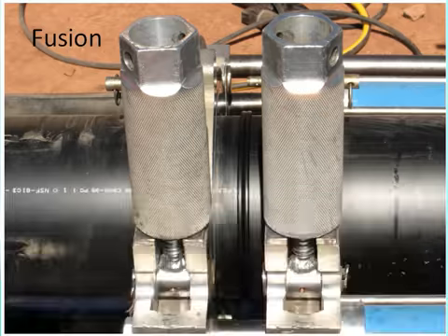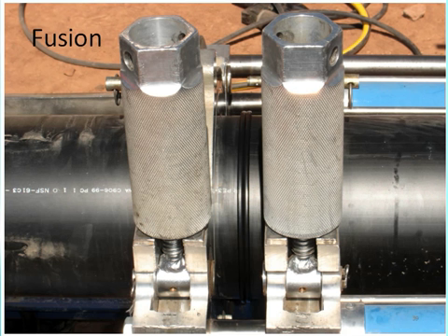And then, we talked a few moments ago about butt fusion. This is a perfect classic picture of a perfect butt fusion joint here. They've had the heating iron here in the middle. They've heated up those 2 surfaces of pipe, and then this contraption here has pushed those 2 pipes together to create a butt fused joint. And like I said, once that joint, if it's properly been done, it cools off, it actually becomes stronger than the pipe itself. And that's been proven time after time in tensile tests.